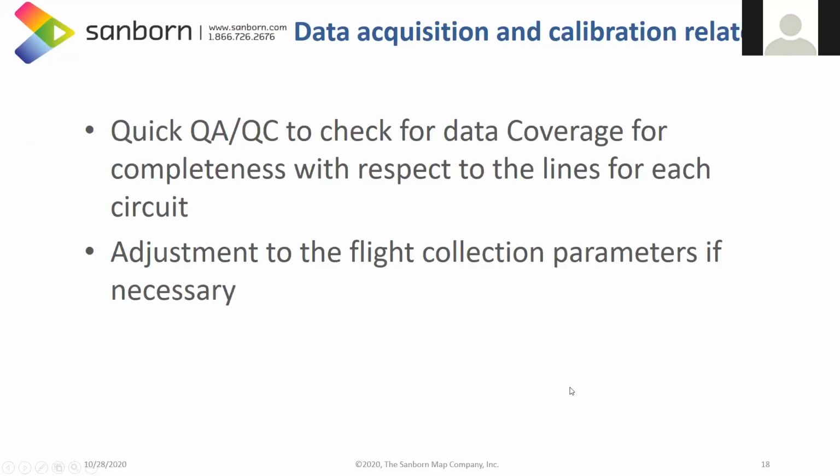Once the data acquisition is done, you need to do a quick QA/QC to check for the data coverage to make sure that you have the complete data set before you leave the area. And also, if needed, you may have to make some adjustments to the flight collection parameters where necessary.